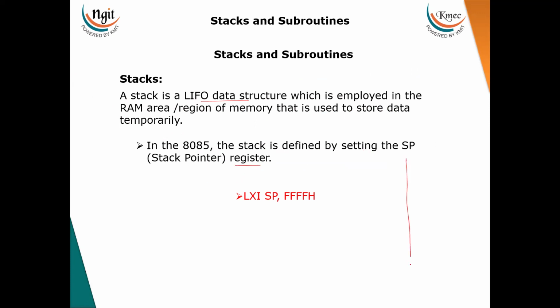Now if this is the huge memory in the processor in the system, then part of the memory is used for storing the data temporarily. This set of locations is called the stack. And always the top of the stack is held by the SP, stack pointer. It is a 16-bit register. In 8085, addresses are indicated using 16 bits, so SP is also a 16-bit register.